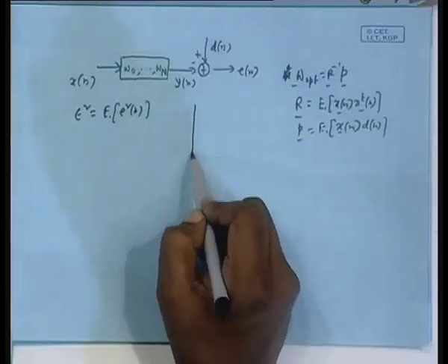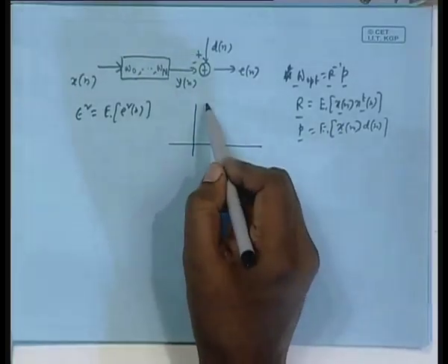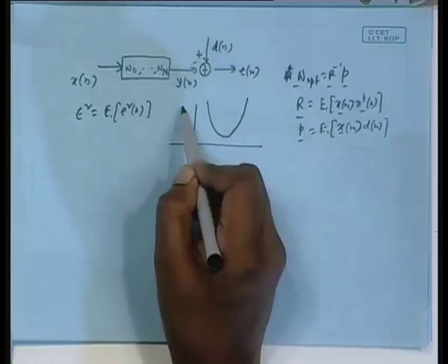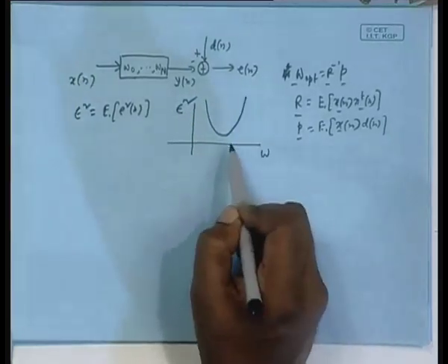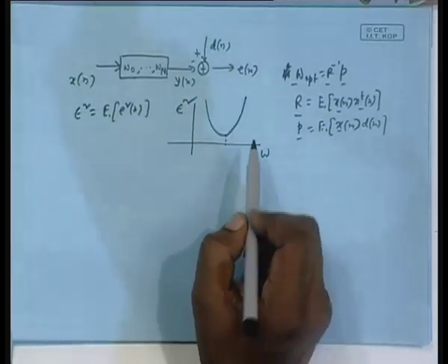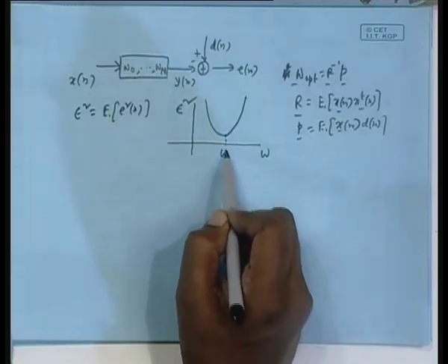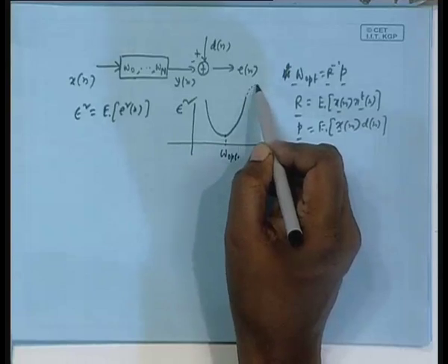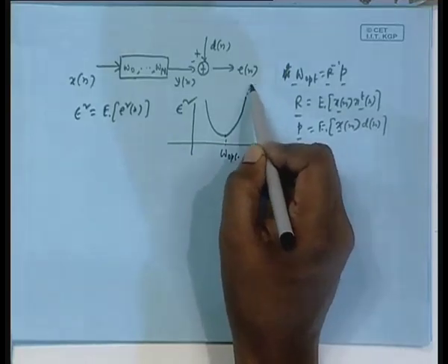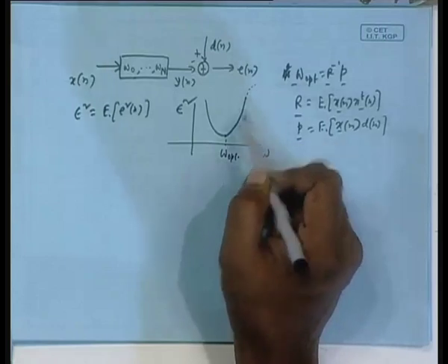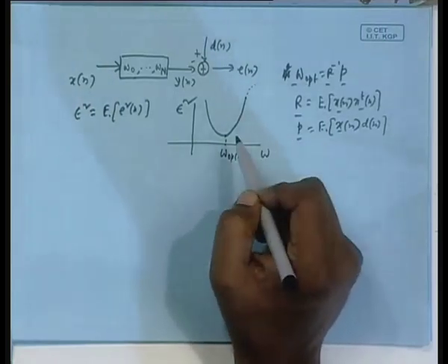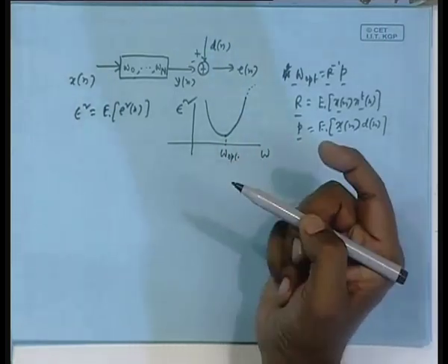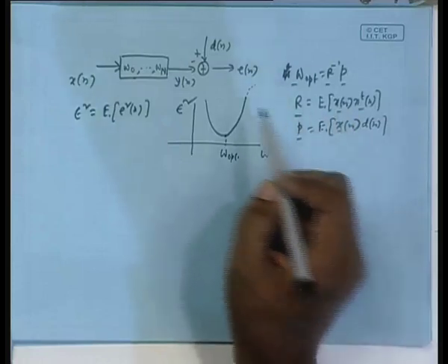Like in the simple case of a single tap filter, this could be the optimum. It can only go up, it can never come down. If it tried to come down, a local maximum would be formed, which cannot happen because it is a quadratic function. If you differentiate it with respect to the weight, you get only a linear equation with one solution. So, it will go up, up.